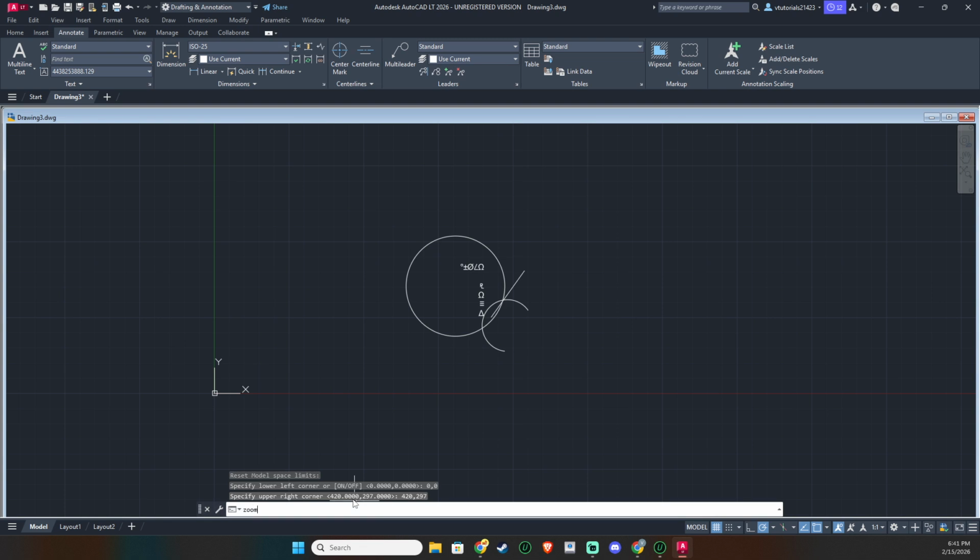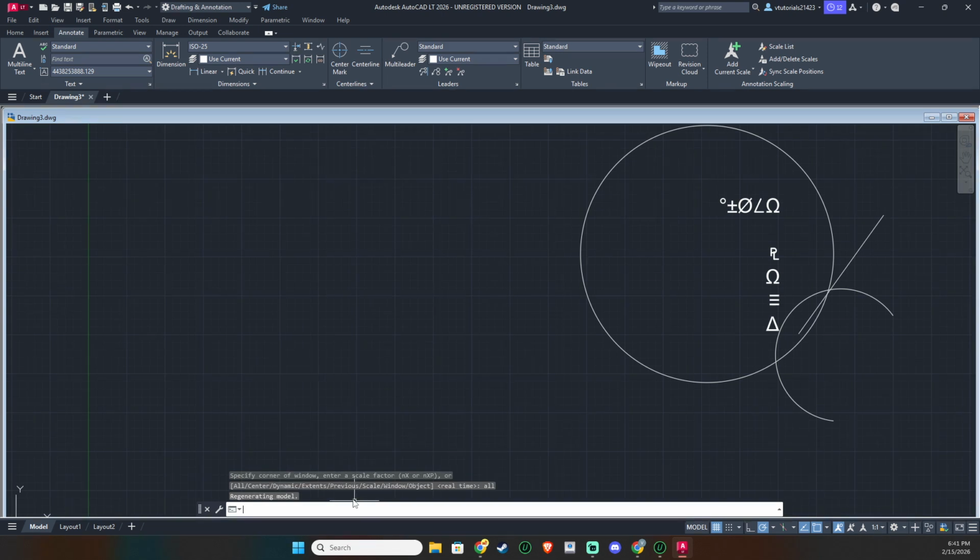That's it. Open your drawing, run limits, confirm what's set, update the corners, and finish with zoom all. You now have a clean, predictable space to design in.